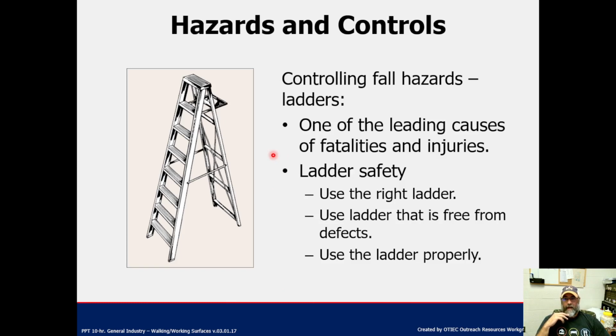I don't know about you. There have been times where I've almost fallen off a ladder. You have to understand how to use ladders properly, using the right ladder. Ladders must be free from defects. If it's missing a step, if it's a wood ladder and the wood's all dry rotted out, if the aluminum ladder is all bent out of shape. Using the ladder properly: this ladder is designed to be opened up like that. It's not meant to be leaned up against something. That is not how it's designed.